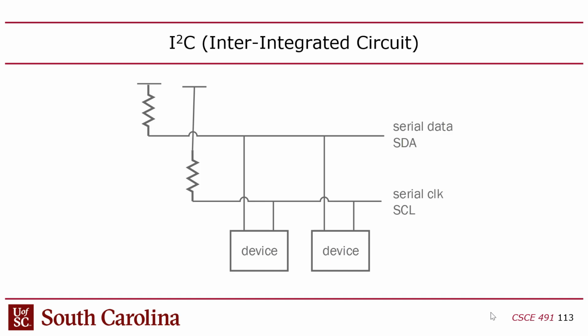Like I showed you guys with UART. You remember that? UART had a start bit and a stop bit on the data line that indicated the start and end of a transaction in I2C. So as a result, we only have 2 wires. And so it's kind of a hybrid approach between UART and SPI. So it's serial, synchronous, half duplex, open drain style design.